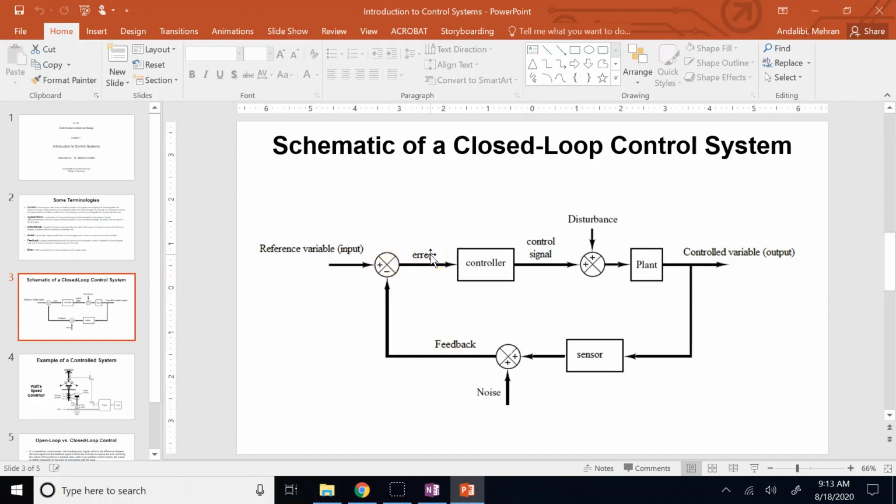That difference here is going to be negative, so you send it to the controller. Now, the controller in this case, if it's a room, is typically an on-off controller, which turns the AC system on or off, right? So if you need heat, it can provide heat.